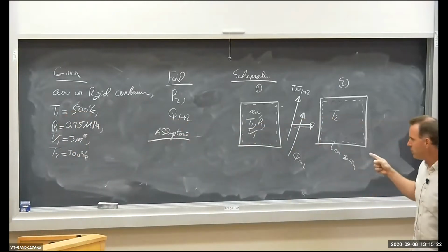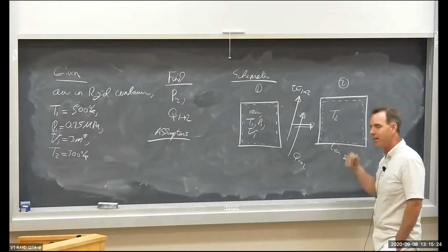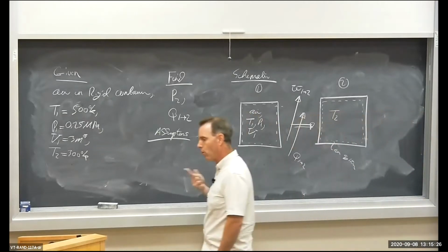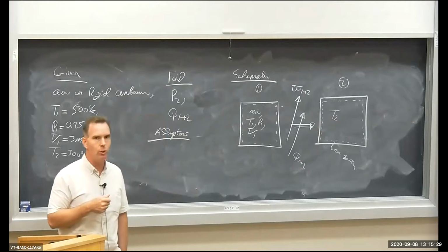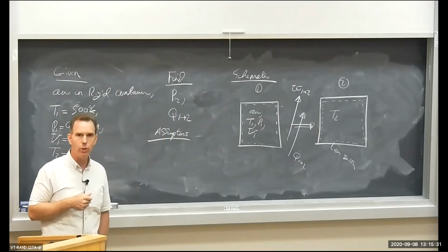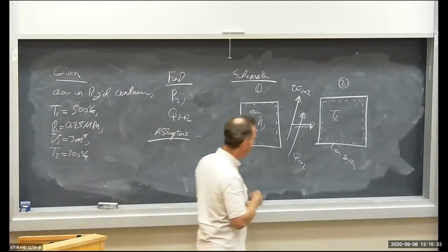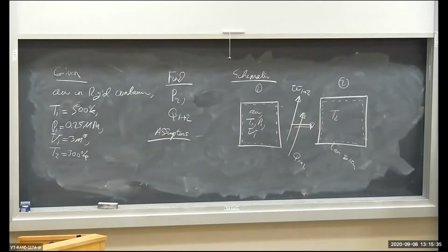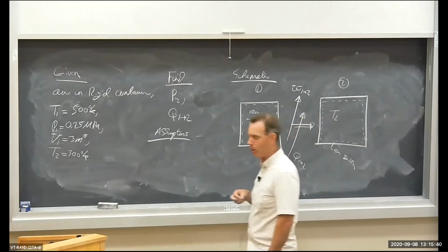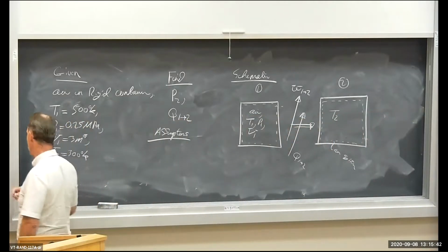Are there any shafts in here? Is there a propeller spinning around and applying a torque with some angular velocity, transferring work in the form of shaft work into the system? Nope, I don't see any shafts, propellers or impellers, so there's no shaft work.